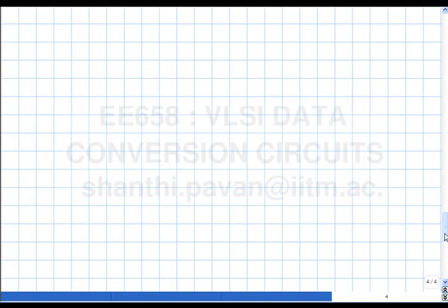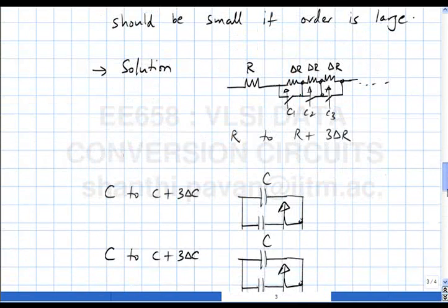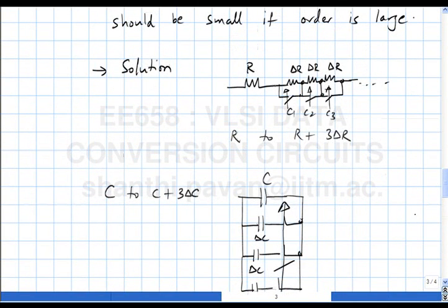Sir, can these be auto-tuned? So what we said now was, I'll somehow measure one resistor on a chip, and the way to do this is the following. I need to measure RC. One way of doing it is to simply measure R, and measure C of one capacitor you make on the IC.